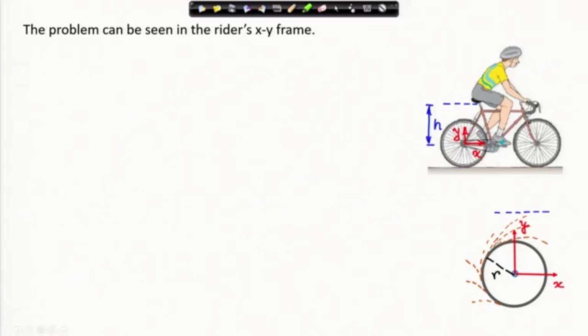Therefore, at all points wherever mud is splashed, it is splashed tangent to the wheel. So, wherever mud is splashed in this frame, it is all tangent to the wheel, but in the absolute frame, for a pedestrian, for example, who sees this person bicycling past, the mud particles will have this additional velocity because of the motion of the bicycle.